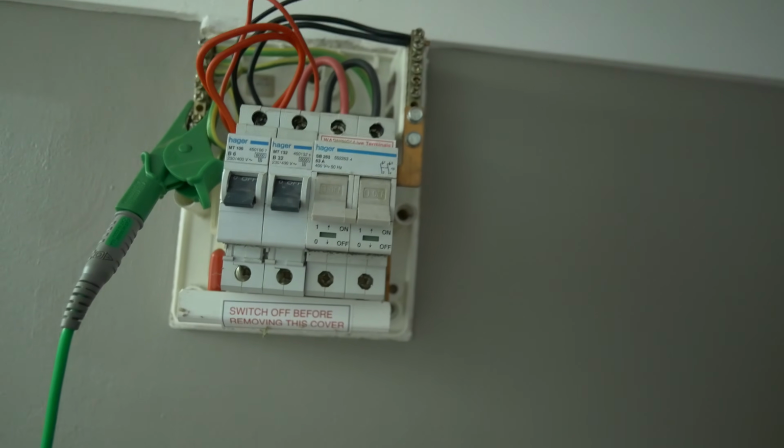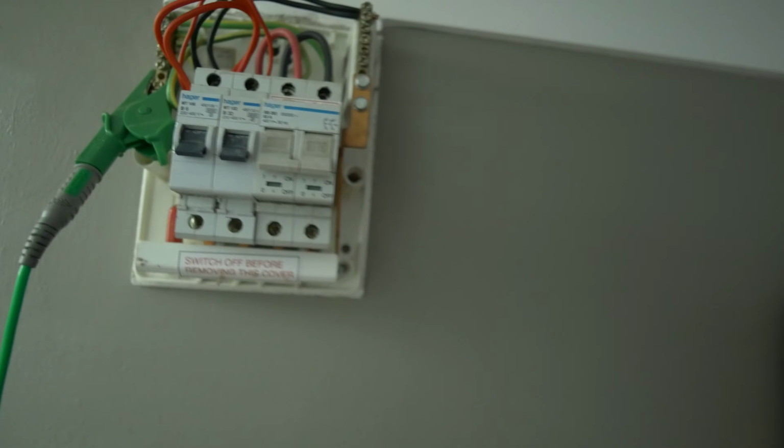Okay, so we can do some insulation resistance testing. Now, there are a few things that will affect the values that I'm aware of. Obviously, all the lamps are in, all the light fittings. There's that light fitting in the bathroom, which I'm not going to be disconnecting out of circuit. There's also the extractor fan. There's the lamps that are in over there as well. And we've also got a USB socket. So there are a few things that are going to affect the values.